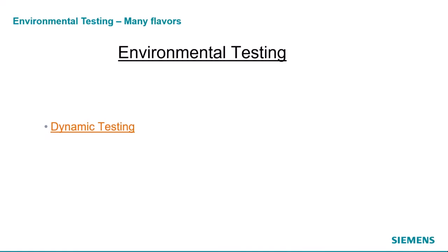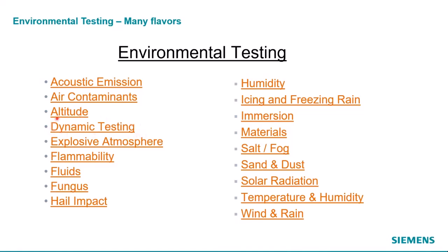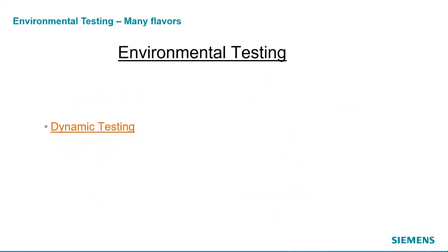That's good. I was wondering, I didn't see vibration testing on the list. I characterize vibration testing and lump it into dynamic testing, because that involves time waveform replication, vibration testing, random testing, sine testing, but also shock testing. Okay, I would say that's a dynamic test too. So it's all contained within this dynamic testing title here. Gotcha. And these are sometimes combined, like temperature and humidity in test chambers that include vibration. That's also a test that's done, where you combine these different environments.